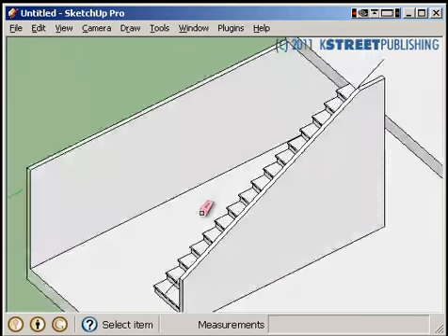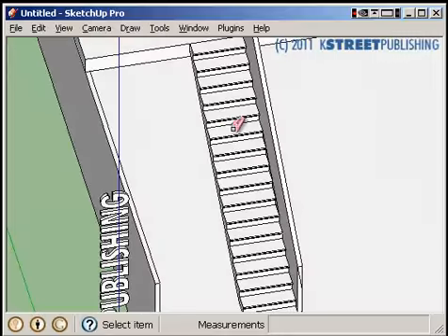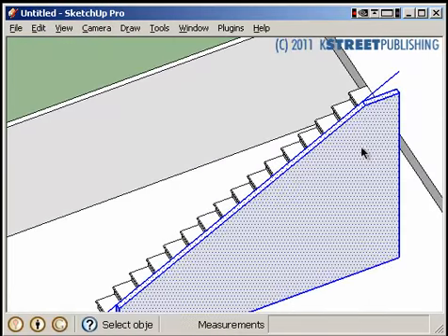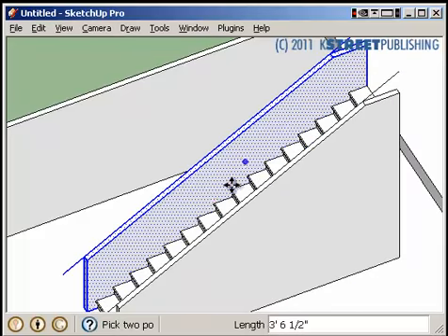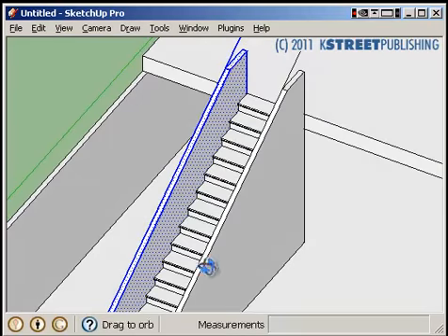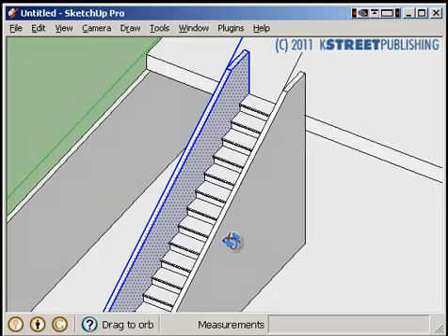Now, I might want to go ahead and just leave that open or copy it onto the other side. If I want to copy it onto the other side, I will identify it. Notice it doesn't highlight the stairs because the stairs are a group. If I didn't make them a group, since they're touching, if I hadn't made the stairs a group, they'd be stuck on here and I wouldn't be able to do this. So now I can copy this, and I'm going to copy it from the intersection point, hit the plus key, and then I can copy it to that location. I can either have a stairway down at this point, underneath the stairs, or I can chop one of these walls and make it open under the stair.